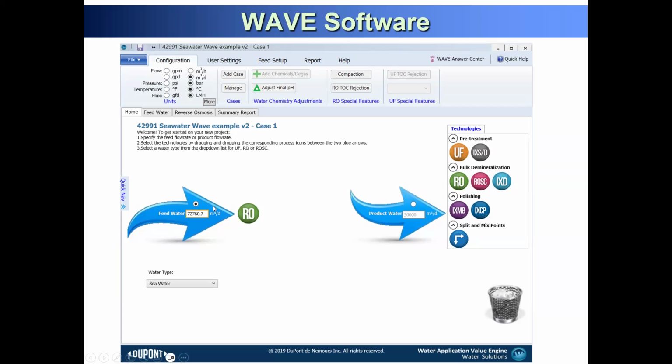So you put like 72 or whatever you want to design for your membrane module, and you want to show us a product. So when you design 250 million liters, this is permeate flux. It's not feed water. Which means your production is 250 million liters per day, not your feed water.